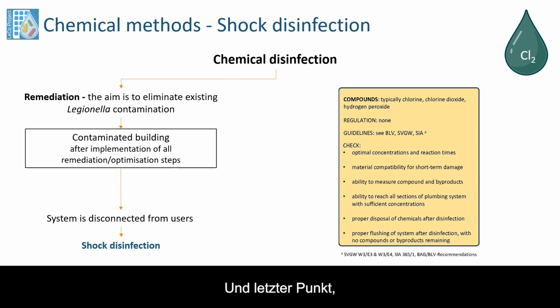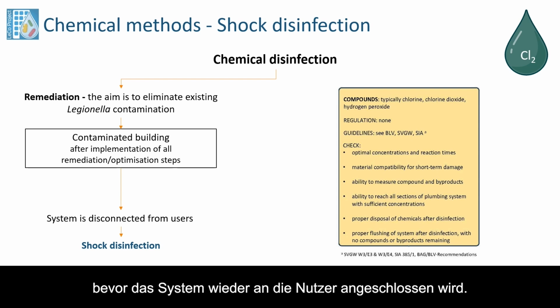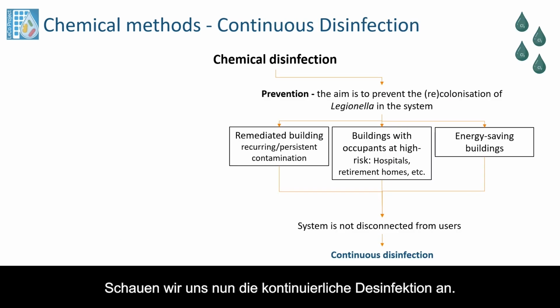The last point to keep in mind for this method is that after the disinfection was applied, there's a proper flushing of the system, because the compounds and byproducts can remain and should be flushed out before it is reconnected to a user. So let's look at continuous disinfection.